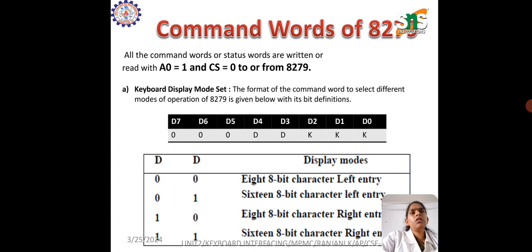The input mode deals with the input given by the keyboard, and it is classified into three modes: scanned keyboard mode, scanned sensor matrix, and strobed input. Under the scanned keyboard mode, the keyboard matrix can be interfaced using encoded or decoded scans, that is, an 8x8 keyboard or 4x8 keyboard. The code of the pressed key with shift and control status is stored in the RAM.